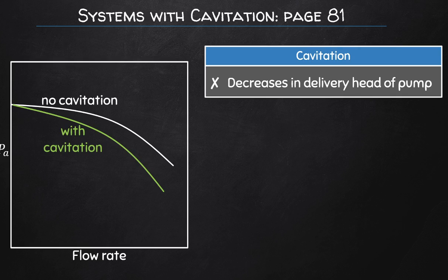Okay, now cavitation will not only damage the fluid movers, but it will also decrease the flow rate for the section of pipeline, obviously because you're now working with gases and vapors, right? So they have more compressibility, and so the pump is just compressing and decompressing and compressing, etc. And a lot of that energy is now not being transferred into kinetic energy.